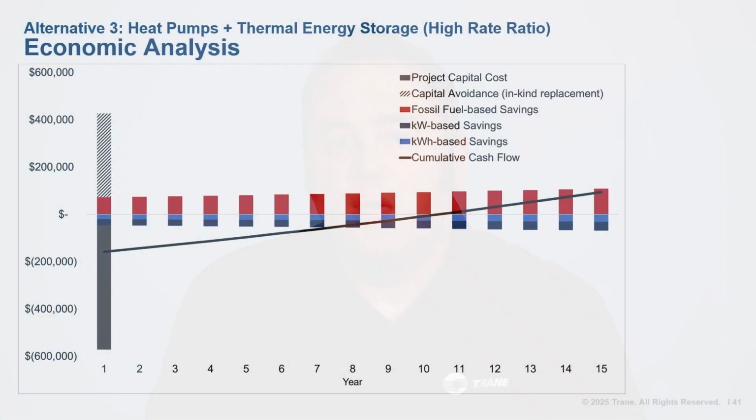During the heating season, the air-to-water heat pumps provide hot water for heating. There is no fossil fuel boiler. Adding thermal storage dramatically changes the math. In our ice storage schedule, the ice tanks provide cooling from 12 o'clock p.m. to 8 o'clock p.m., mostly during the on-peak hours.